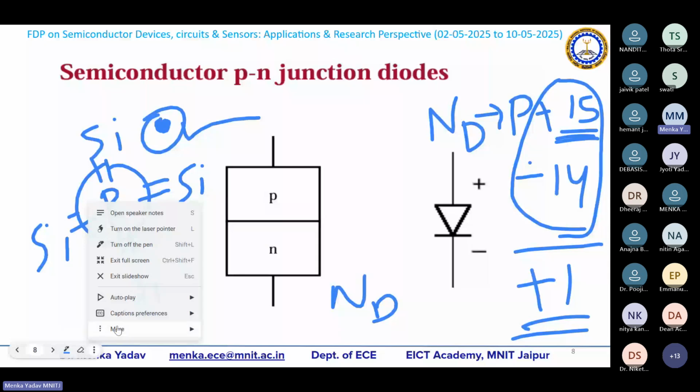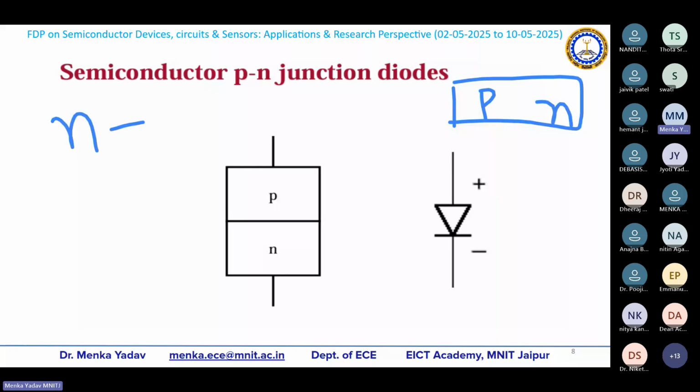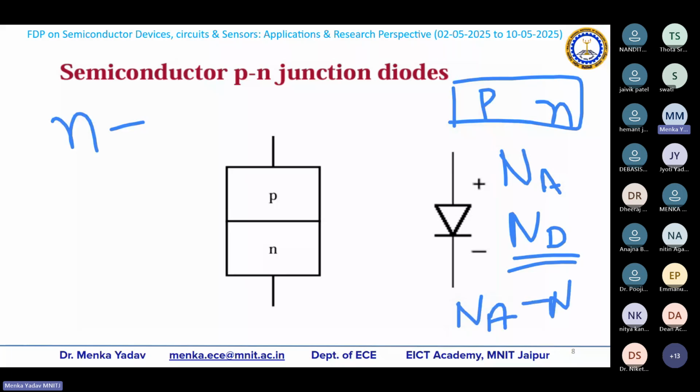We will now consider the equilibrium of charge. Let us consider a semiconductor bar as shown in the diagram. It has some P and some N doping, meaning both Na and Nd doping is done. Now what type of material can it be considered? To decide, we take Na minus Nd. If it is positive, it is p-type. If it is negative, we consider it n-type. That's the formula. Now for any semiconductor, we have to figure out the charge neutrality equation. This again comes from the conservation of charge.